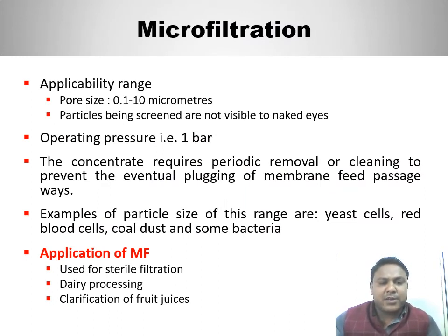Microfiltration. Microfiltration usually serves as a pre-treatment for other separation processes such as ultrafiltration and a post-treatment for granular media filtration. The typical particle size used for microfiltration ranges from about 0.1 to 10 micrometers and operating pressure is around 1 bar. In terms of approximate molecular weight, these membranes can separate macromolecules of molecular weights generally less than 100,000 gram per mole. The filters used in the microfiltration process are especially designed to separate starch, bacteria, fat, molds, yeast, and emulsified oils.